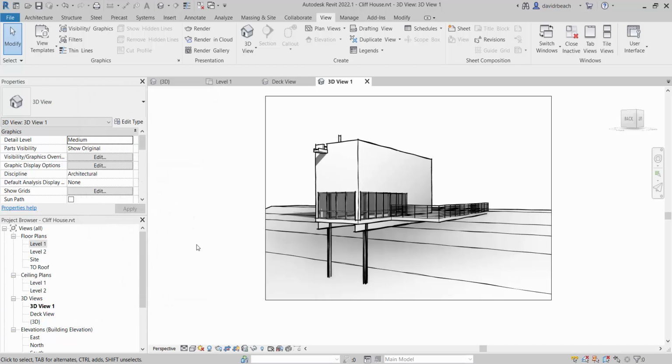So, kind of nice, but if you'll notice, the camera comes in as a default at ground level. Specifically, it comes in at 5 feet 4 inches above ground level. So I was on level 1, and it placed the camera at 5 feet 4 above ground level. So I'm still flat looking across, which is a really good default, and a default that we often want to use. But if I want to move this so that the camera is down and then looking up, I need to be able to do that in an elevation view.